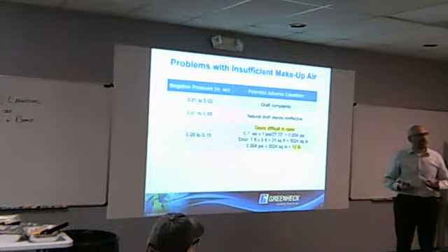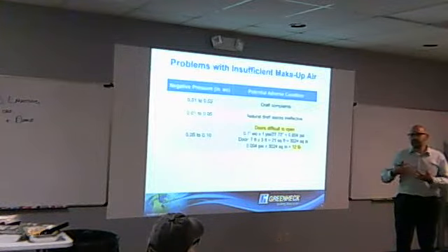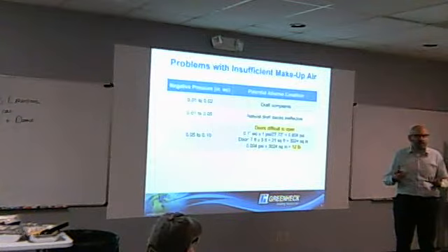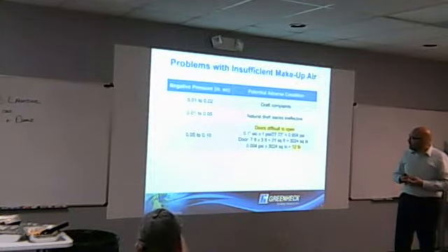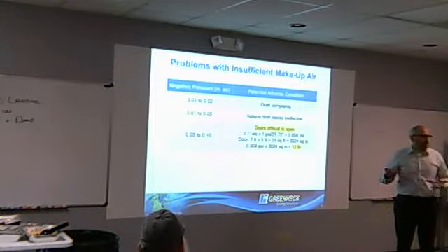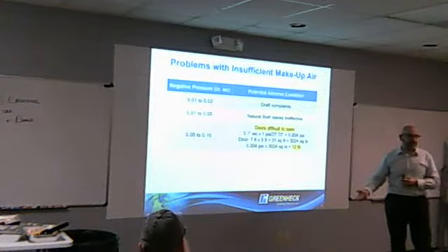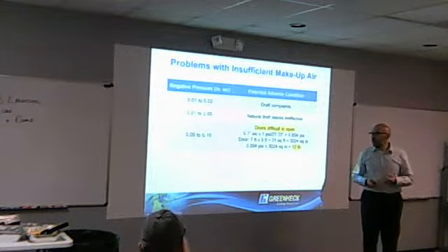Maybe that's annoying to somebody, but most of the times I reference cold because people recognize that. So it's 0 degrees, you pull this air in, that's not good. Natural draft stacks become ineffective. If you do have a gravity or natural stack and you start going negative, you could be pulling those products of combustion down into the space and be in bad condition.